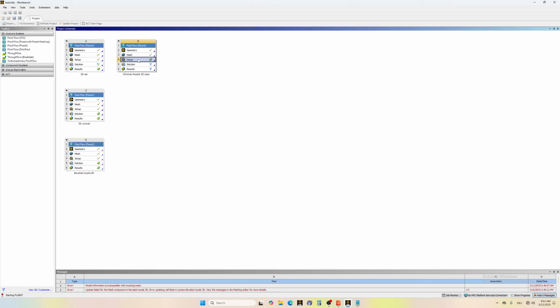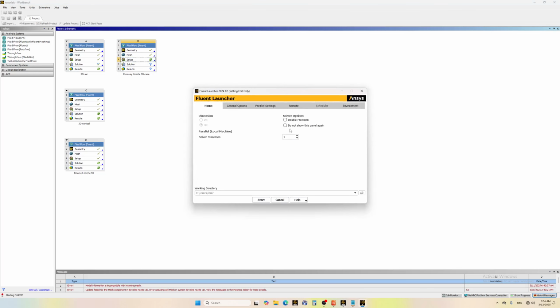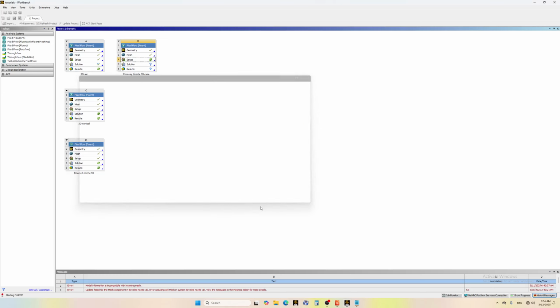Okay, let's start Fluent. And now double precision, always double precision when we want an accurate result. Here you can choose to display the mesh or not. If it's a huge mesh, I'm talking about many millions or tens of millions, it's not a good idea to display the mesh because it takes a lot of time and it's not really important to see the mesh in Ansys Fluent. Here for processes you can choose for Ansys Student. I can choose many more since I have an Ansys license. Okay, start.